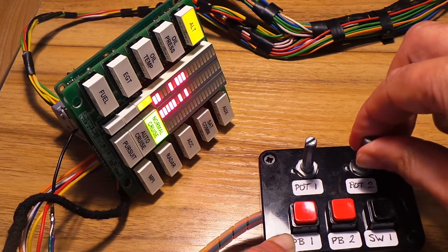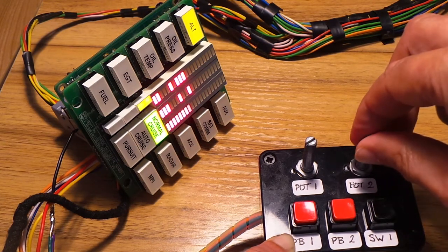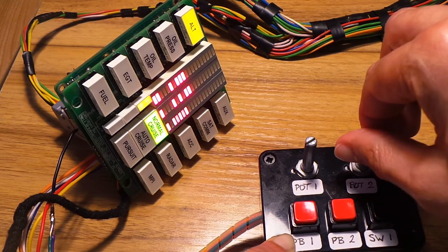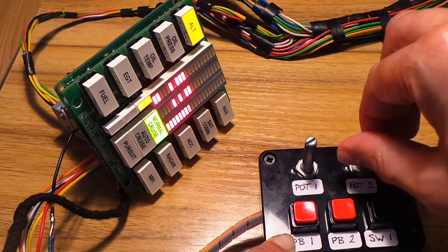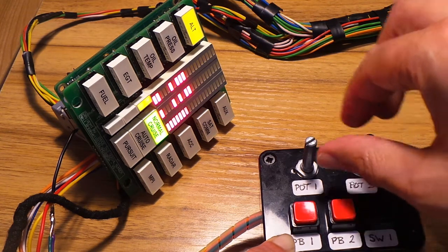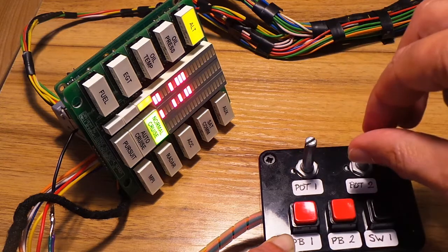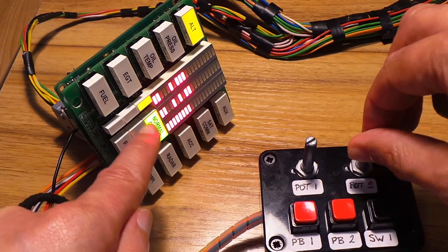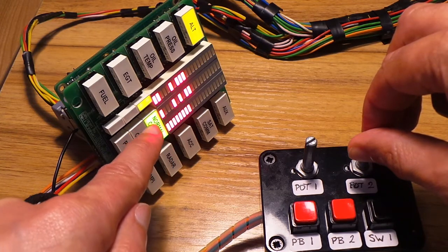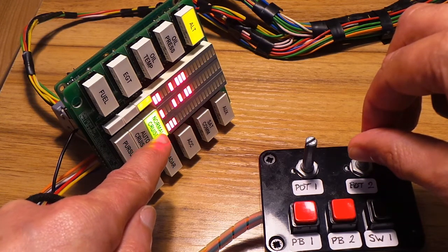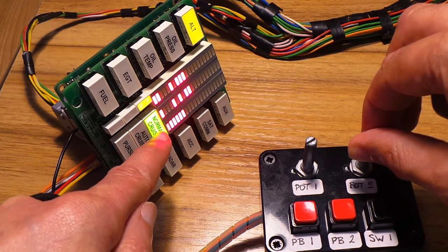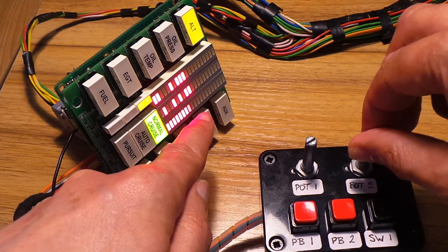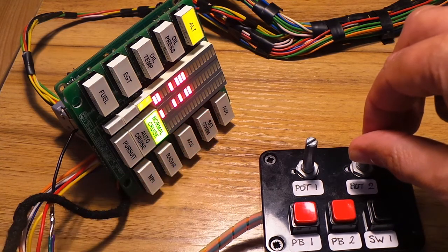We don't actually vary the brightness in output test mode or input test mode, because obviously what we want to do is just see that we're receiving inputs. Brightness variation is only enabled in the show mode or the normal running mode. So they're the three analog displays there. They're effectively binary values with the least significant bit at the bottom. So you can imagine that this is the least significant bit, and the most significant bit from the analog to digital converter is at the top there.